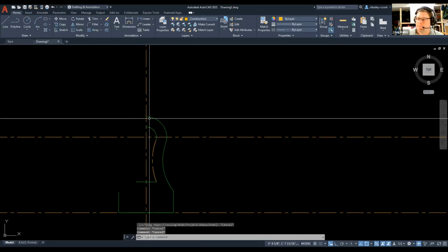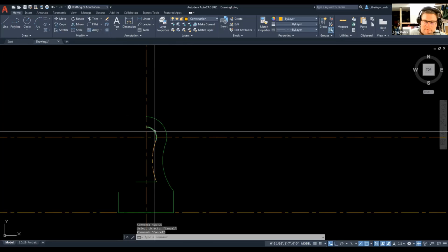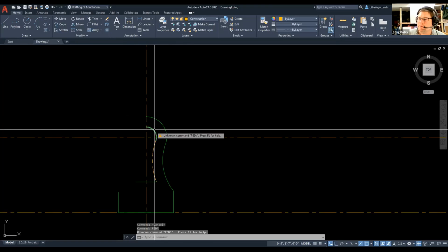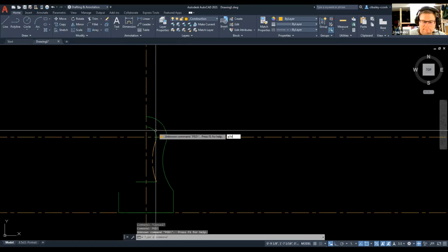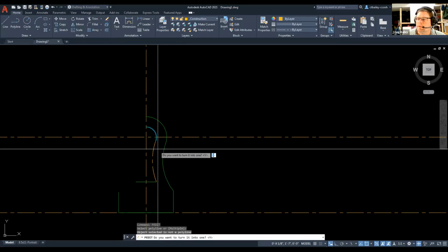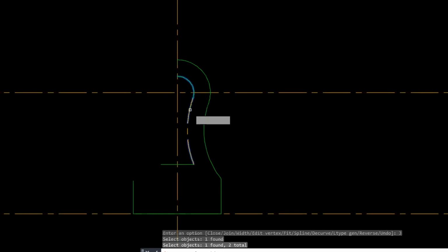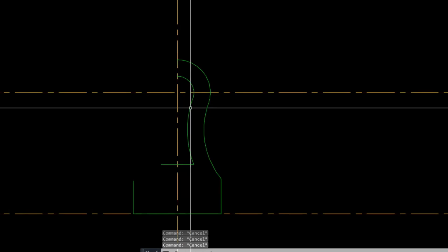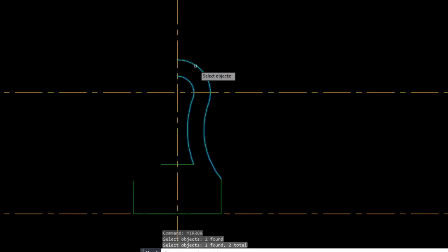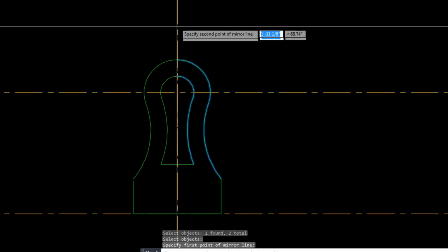that. And I'm going to mirror. Oh, let me poly edit that one. Poly edit the inside. P edit. Here. This one and that one. And now we'll fire off the mirror command. 1, 2. From there, and we're going to go up.